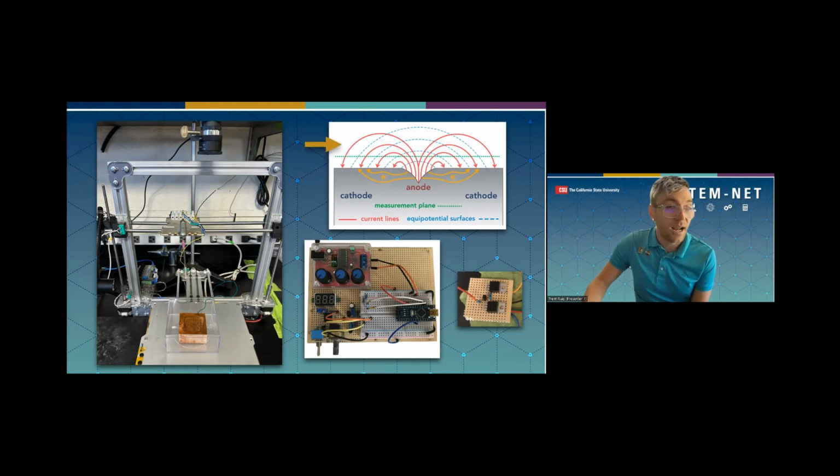The SVET apparatus will scan over the surface of the corroding metal and measure the equipotential surfaces that are permeating from the corroding metal. To drive corrosion, we're utilizing a power supply built from a previous class and additional drive circuits allowing us to oscillate corrosion.